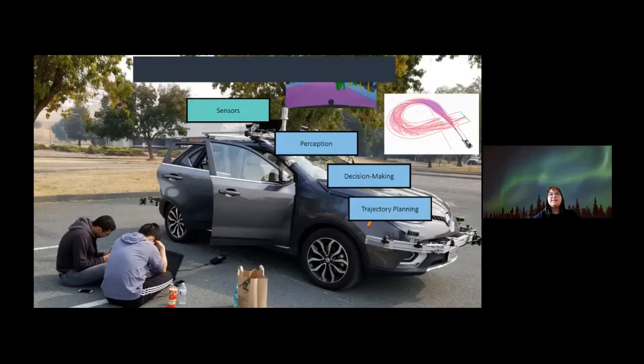So typically all this gets passed down to some low-level control. And this low-level control is basically going to be the middleman between the output of the decision-making and planning and the hardware itself. So basically, this is going to convert these planned motions into inputs. So if we think about the car itself, it's basically going to be the piece that turns a planned path, say a particular lane change or how you will make a right turn, and turn it into the car inputs. So this would be your steering, your throttle, and your brake. So this will sort of be this very fast reactive decision making that will basically be actually maneuvering the vehicle itself or the robot in general.